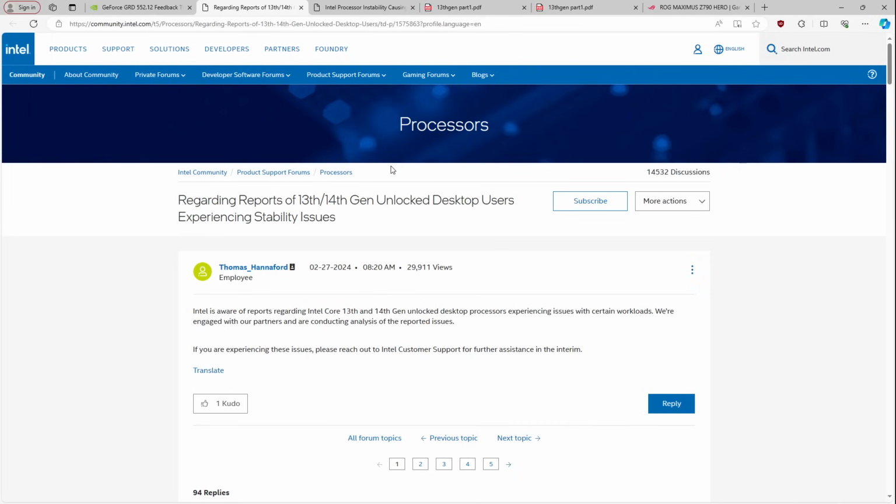That to me seems way worse. But let's say you are concerned about the chips degrading, just lower the TJ max. I think that's the best option, because at a lower TJ max, if the CPU is power throttling, it's going to thermal throttle earlier, so it's just going to thermal throttle at lower power draw. The lower temperature alone is going to significantly help with all aspects of degradation, right?